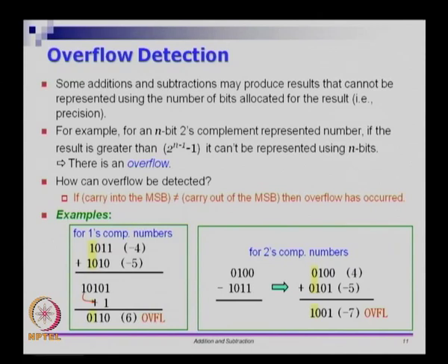Typically what computers do is, if something like that happens, the circuitry can detect this overflow and set a flag called the overflow flag. If you have done 8085 programming, 8086 and so on, they would have taught you about this set of flags that are there in the processor. So, the addition or subtraction of two numbers can result in the overflow flag being set, which means the result that you have is not correct. Something has happened, because it is not in the range that is represented.